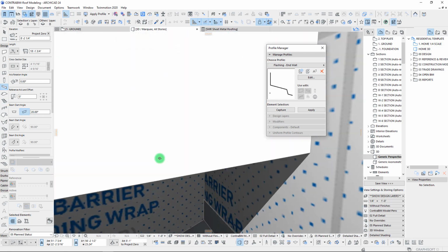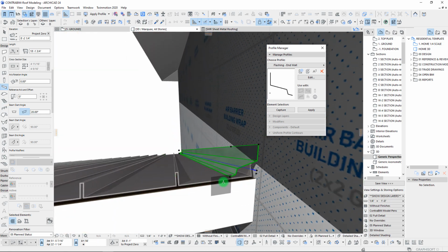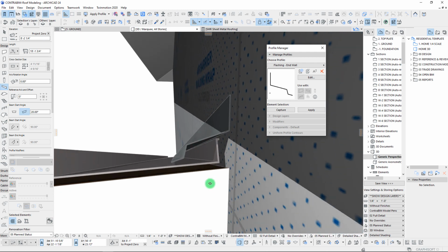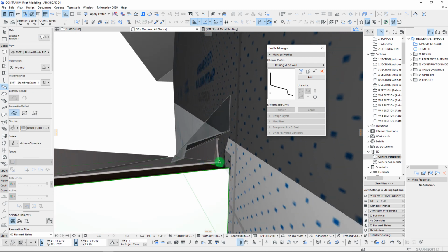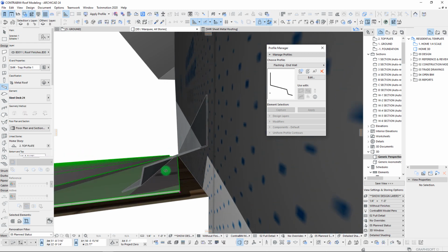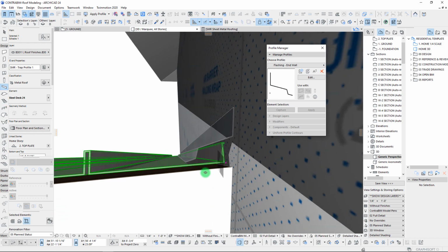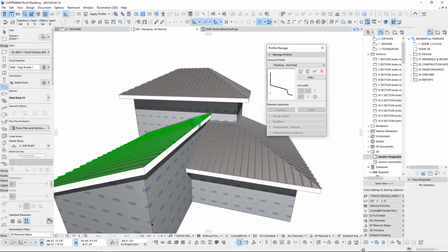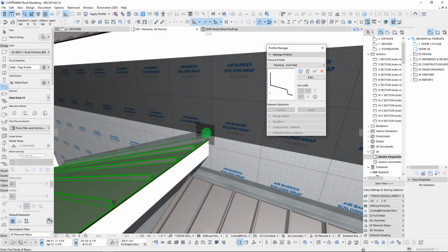And with the detailing here, obviously we would want to make sure that we at least have one additional rib here in the back. If this sheet metal element was like that and a little bit short, then that would not work out so well. So we need that additional rib there in the back to channel that water down. So okay, that is one condition here.